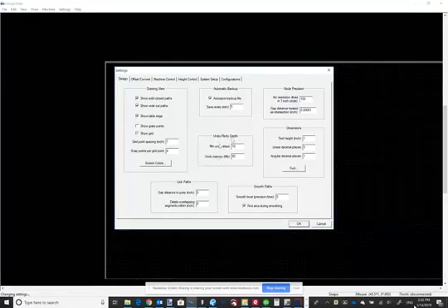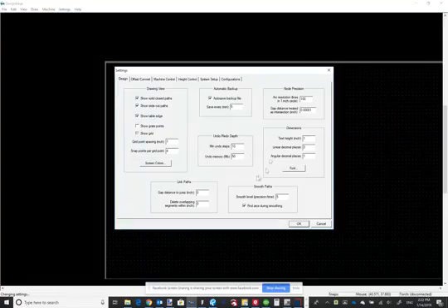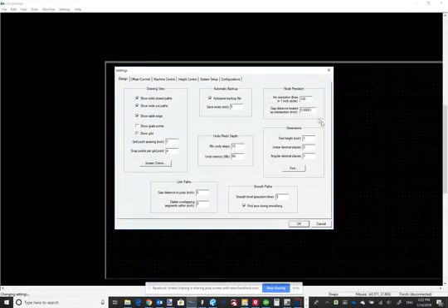It adds this undo and redo depth setting. I always leave it factory, so that doesn't really help me, but it does let you increase the number of steps you can do to undo. It lets you adjust your node precision. Both of those things I usually use as standard unless I'm doing design for my laser. Since it adds the dimension tool, it also adds these parameters for you to set the text, the font, height, and decimal places for your dimension tool. It adds this delete overlapping segments so that if you had multiple paths on top of each other, those infamous Plasma Spider files, you can actually add a number in here, very small, and it'll delete paths that are overlapped. And it lets you set the precision and turn off finding arc smoothing. So I leave that factory. So again, not big help, but it adds that option with advanced design.